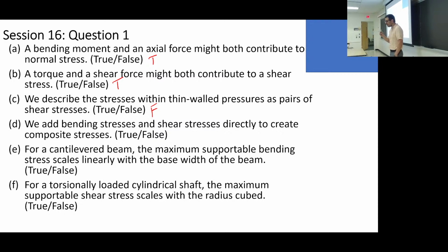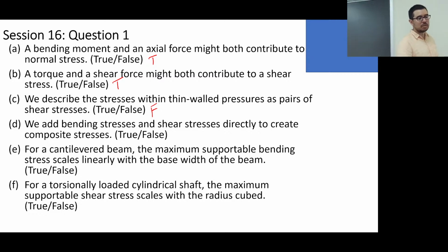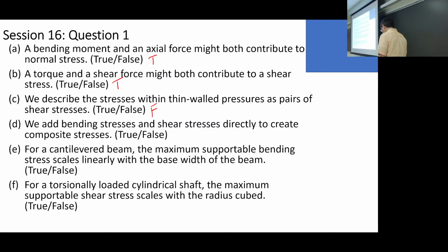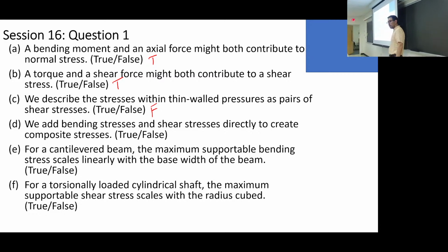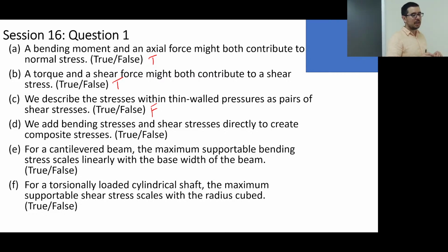But as we derived, these are normal stresses. So we don't typically think of pairs of shear stresses, but pairs of normal stresses. Okay, sigma 1 and sigma 2. And if it's a sphere, then there's no shear stress equivalent, at least not in the plane. There is in 3D. All right, we'll get into that later.